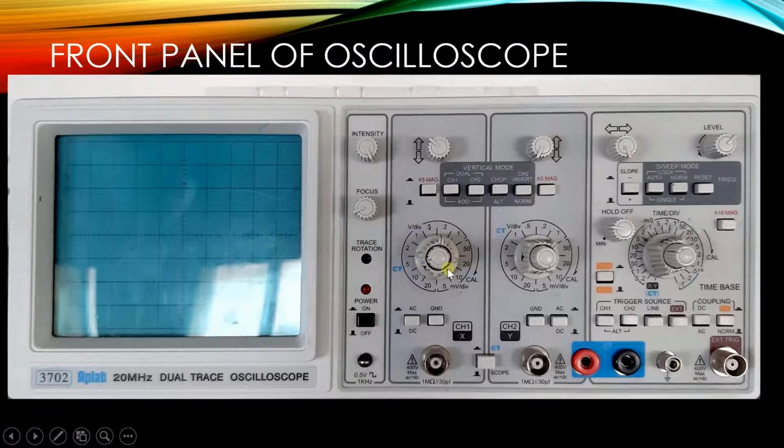So this rotary button is volts per division, which controls the volts per division of channel 1. Similarly, this is the volts per division of channel 2, and this is AC and DC. If we press it, it becomes DC. If it is pressed, it is AC. When it is unpressed, this is DC, and this is the ground button.